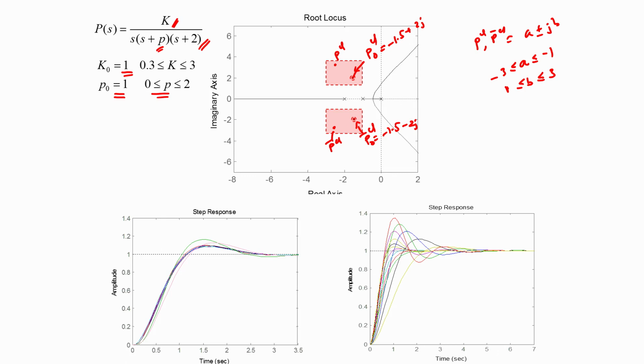So, in this case what we are saying is that if you are not willing to pay such a high price, if you are not willing to invest in controllers with such high bandwidths, and correspondingly we are also okay with permitting a much larger variation in the closed loop response of our overall control system, then how do we undertake systematically the design of the feedback controller and the pre-filter that will allow us to get a control system whose closed loop response varies within the particular bounds that have been indicated by these new set of step responses, within this particular bound and no larger.